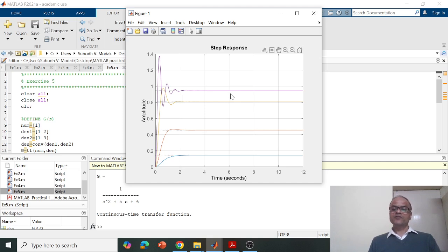And 0.95 is very close to 1. So now this controller is doing the job of tracking the reference input much better, because the output of the feedback loop is closer to the reference value. Although the steady state error is not completely zero, which means that the output is not exactly tracking the reference input, it is pretty close to the reference value.